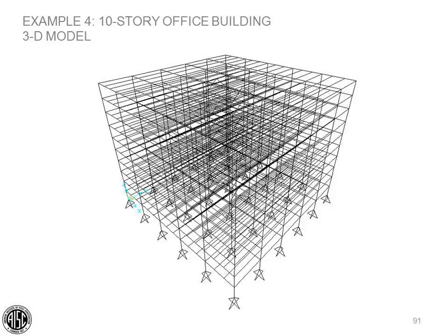We built the full 3D model, including all floors and roof, the brace frames, the moment frames, and including all gravity columns as well. We included all gravity loads and wind and seismic loads in each direction. Note that if we had only used 2D models for each direction, we would need to add dummy columns to represent all the gravity columns leaning on the frames for stability.